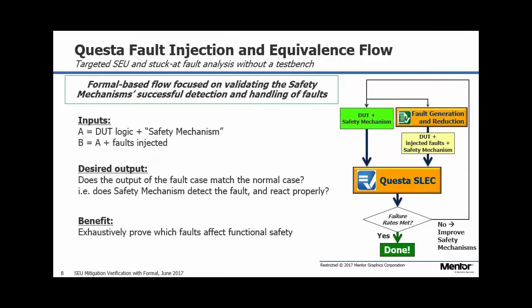Dominic Murphy, ARM. You mentioned cut points when answering the other question. I assume that's where you assert the behavior up until the cut point is the same between your two designs, and then you assume it's the same onwards. Well, actually, what you'd have is a conditional cut point. The condition is a signal which formal can assert whenever it wants. When it asserts that signal, it gets the faults injected. When it doesn't, it's just connected as normal to whatever logic should be driving it.